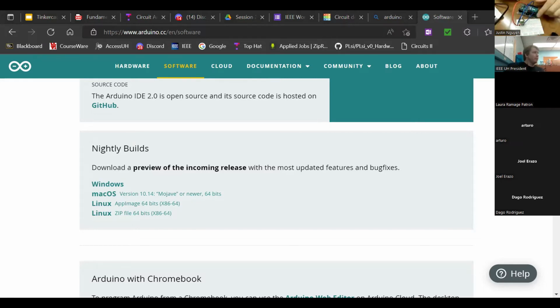Okay. So I see there's a 5 volt here. There's a ground here, and then we just connect it to a pin. Connect the ground first. The Nano setup is a little different, but you just have to read the pins. And then the middle one you have to connect to an analog, and that will be 0.